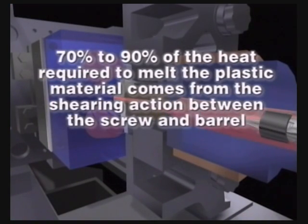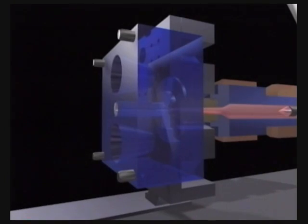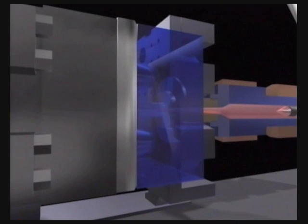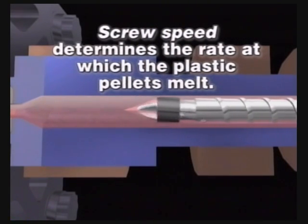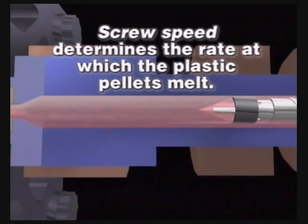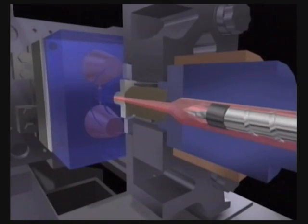70 to 90% of the heat required to melt the material comes from the shearing action between the screw and barrel. Therefore, screw speed is a critical parameter for controlling melt temperature. Screw speed determines the rate at which the plastic pellets melt. It is necessary to maintain a slow, steady, consistent speed to evenly melt the material.